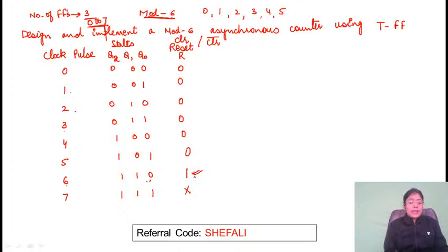Now, can you determine in what case it is resetting the value? When do we have to clear the value? Now, before designing the circuit diagram, let's consider one more thing. If the input is Q complement and you are using clear complement, not, then it will be using the OR gate. If it is Q complement and clear, then it will be using the NOR gate.